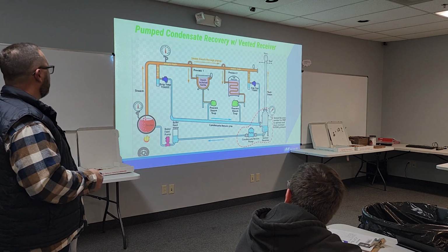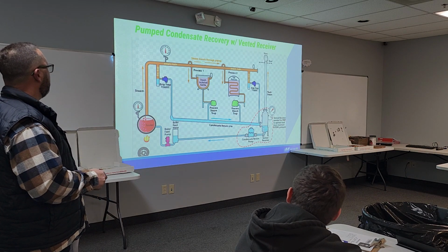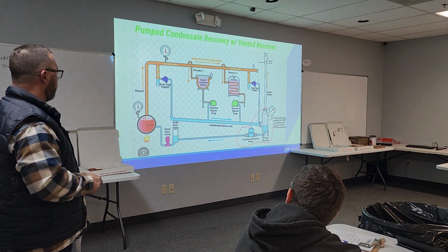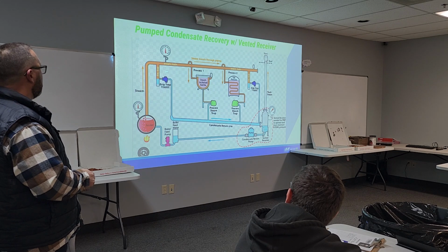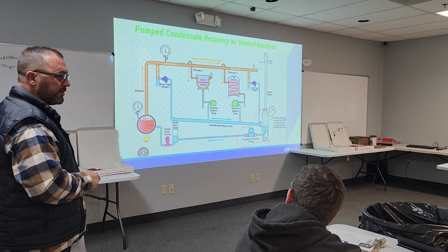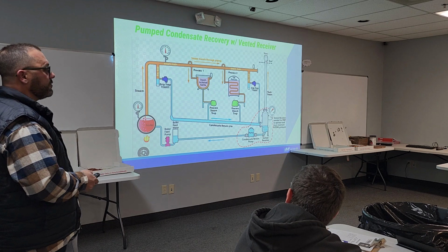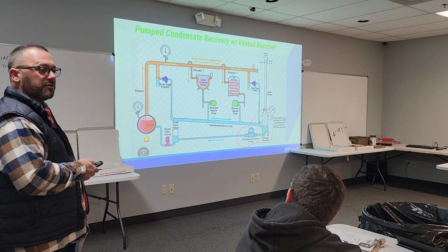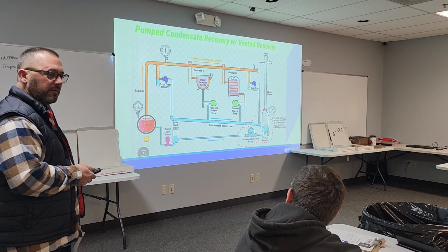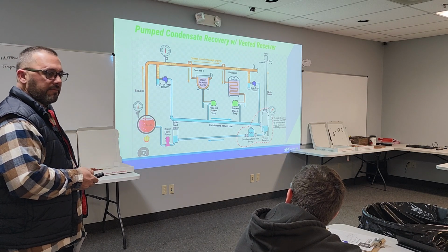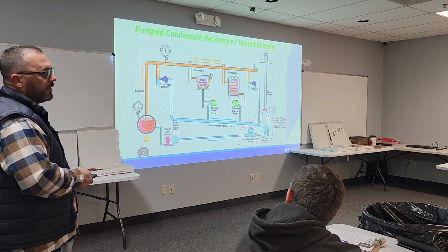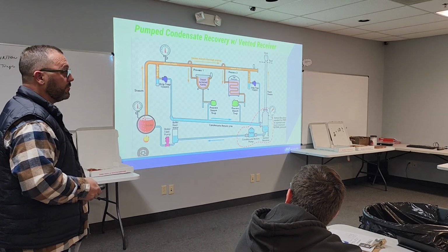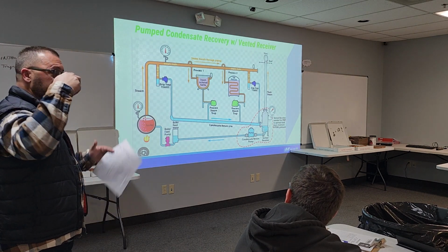So my first choice on a drip trap for a steam main, if we're above 30 psi, would be a thermodynamic trap, and we'll get into more of the weeds on that. It's got a disc in it, and we've got an animation on that, and we'll talk about that. But that'd be my first choice. Tom might have a different one. What's your first choice for a steam main drip above 30 psi? Are you a bucket trap guy? Yeah. Yep, inverted bucket. Inverted buckets do great when people have dirty steam. We'll see that the head and seat is in the top of that, so dirt falls.